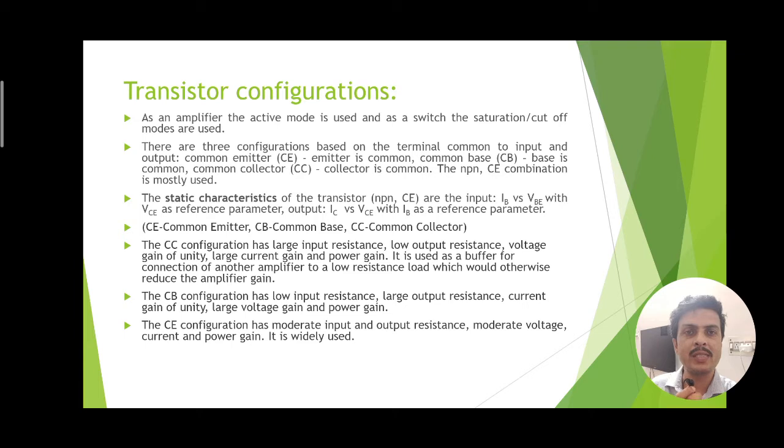impedance, output impedance, all these things, such as the common collector configuration is having high input impedance and low output impedance. That is why common collector is very much essential for the type of operation in which impedance matching is required. The voltage gain of the common collector is unity. The large amount of current gain and power gain is also achieved using common collector configuration.